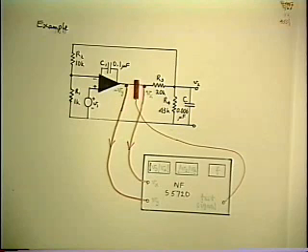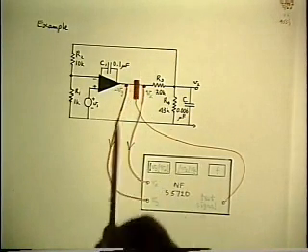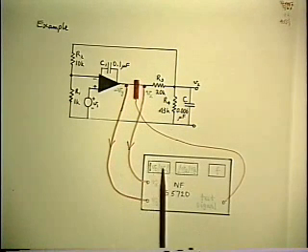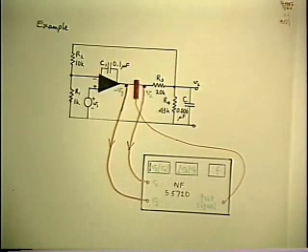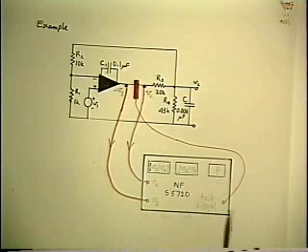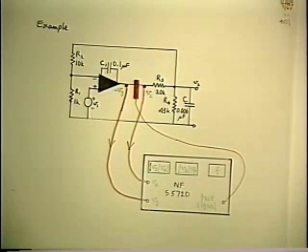But the AC clip-on current probe is a transformer, because inside the probe head is a magnetic toroid, which is split in order that you can slide the head into two pieces and get the wire inside it. It's a one-turn primary transformer, where the one turn is the wire that you clip it around. And it's got lots of turns around the toroid. I don't know how many turns. So it's got a big ratio anyway, and then the output goes into the termination. And it reflects current according to the turns ratio, like any decent transformer.